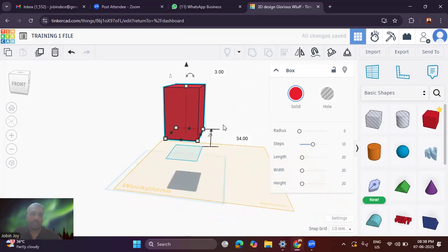So next is how we can change the size. Now see, the size is 51 by 73, right? Here you can see the grips, these white square boxes or black square boxes. This is what is called grips. When I click this white grip, what happens? Two values are displayed. That means I can change two values at a time.